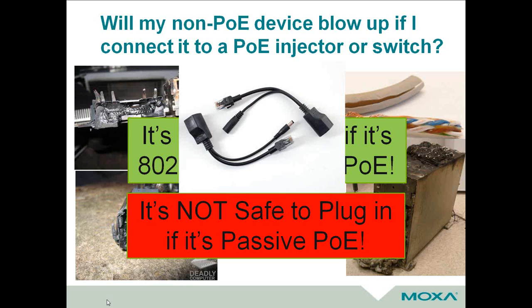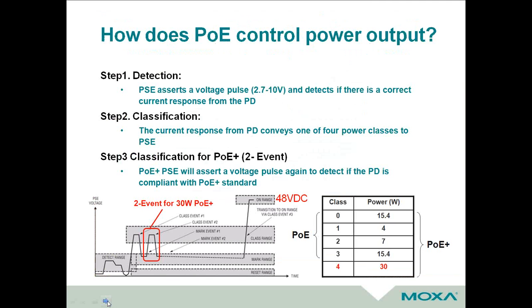It's inexpensive, but there are no protections, and you definitely can easily melt your devices, start a fire, all kinds of safety concerns with it. So please shy away from those passive PoE devices out there. Stick with the standard-based stuff.